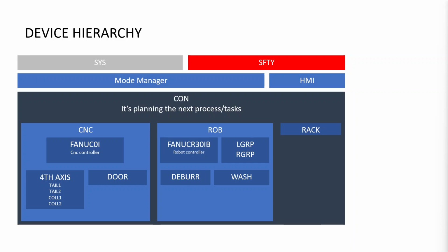And so the conductor really just wants to issue high level tasks, and allow its children devices to distribute those down to the low level control, like physically setting an output on an SMC valve, for example. So the idea is that the task in the conductor should read pretty cleanly to anyone walking up to the project, whether or not they understand automation or not.